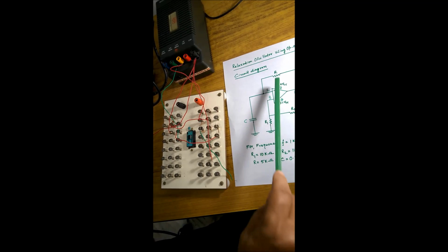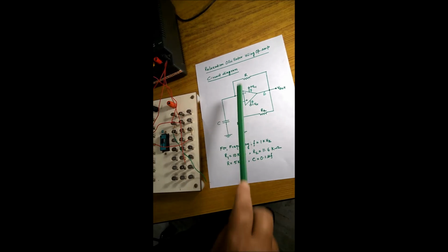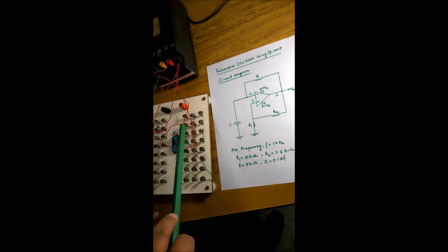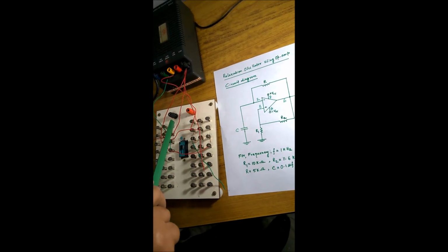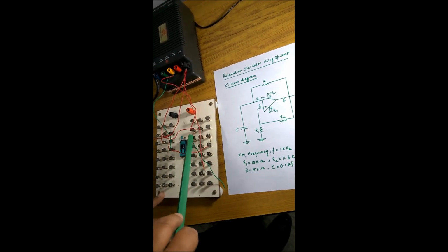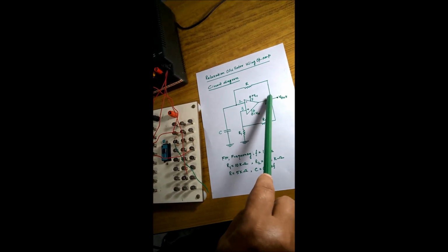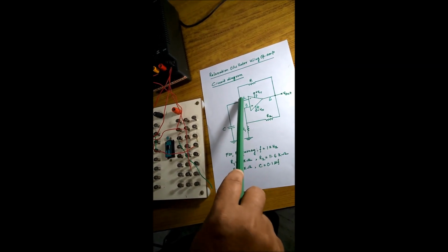Next, you come to the R. R is after the design we got: R equal to 5K. You cannot use the other pins, because these are pins 1, 2, 3, 4, 5, 6, 7, 8. You cannot use that. Therefore, it has to be connected: one end will be connected to 6, and the other end has to be connected to 2.